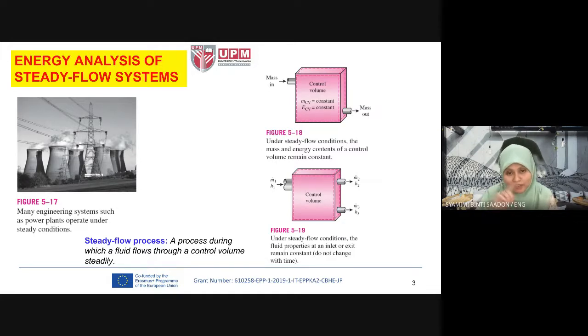So normally in the mathematical equation, the differential form of these properties, pressure, temperature, mass, etc., with respect to time is negligible or zero. So it doesn't depend on time. Under steady flow conditions, the mass and energy content of the control volume remain constant. Many engineering systems such as power plants operate under steady conditions. So we can actually